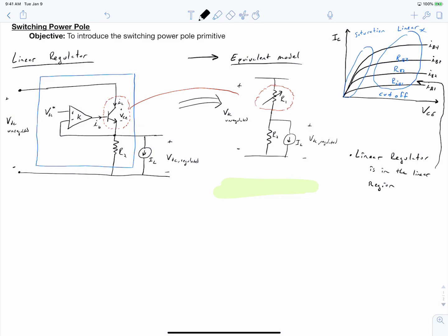And because of this fundamental voltage divider structure, we've commented that we have a very low efficiency for large differences in voltage between the input and the output. Furthermore, by observing this circuit structure, we can say that we have unidirectional power flow. And similarly, our voltage transformation goes one way.